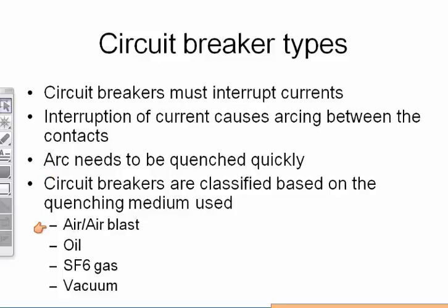So in terms of quenching medium, you have air or air blast, oil, SF6 and vacuum. Has anyone heard of air blast before? Yes, what voltages would you use an air blast circuit breaker? What voltages typically? Yes, very high voltages, even much more than 66 kV, Nicholas.